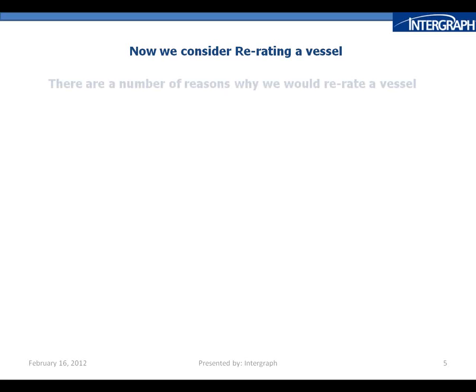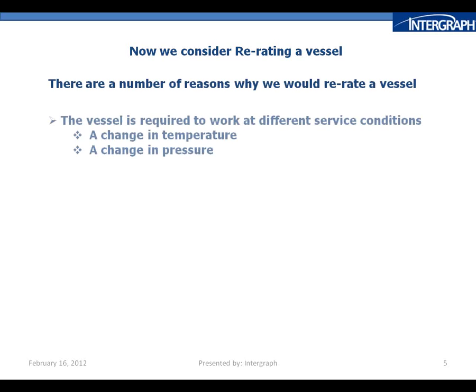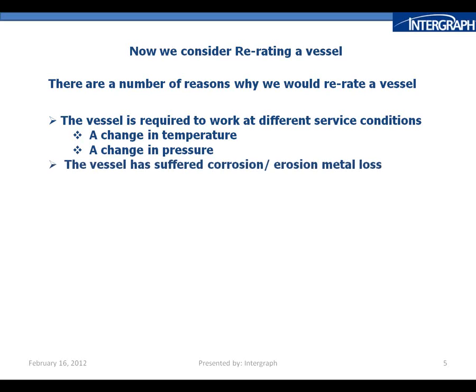Now we consider re-rating a vessel. There are various reasons why we would want to re-rate a vessel. Perhaps there's been a change in the temperature. The vessel may have suffered some corrosion or erosion. Over time, vessels do suffer to some stage or another. Perhaps a repair has been done.